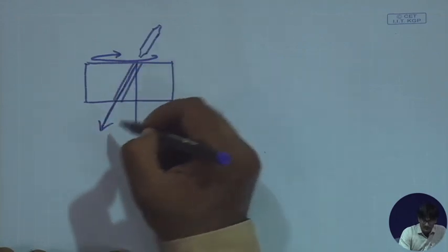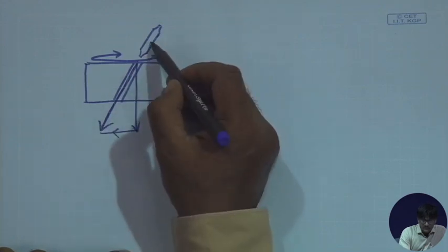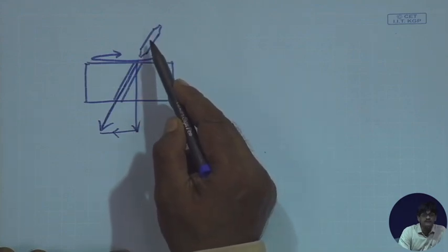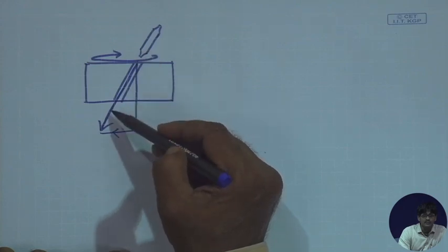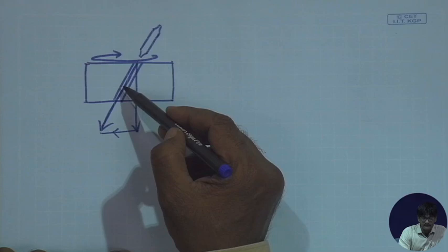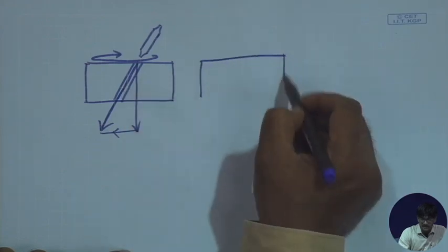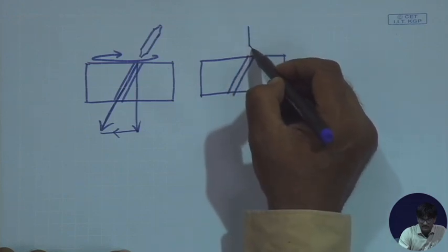So, you have to orient the job, orient the cutter physically in this direction. Otherwise, you will not have a cutting action, but you will have a slapping action.